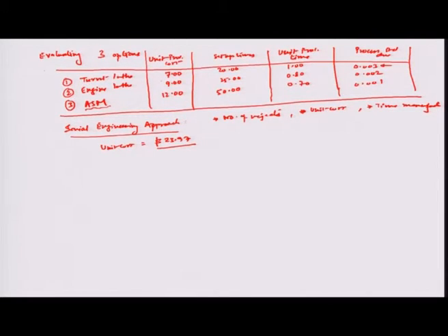And the setup time provided in this particular case was about 20 time units. Let us say this is in minutes, so the setup time was exactly 20 minutes for the turret lathe, and the number of rejects, which was a measure of the quality in this case, happened to be about 465 units.